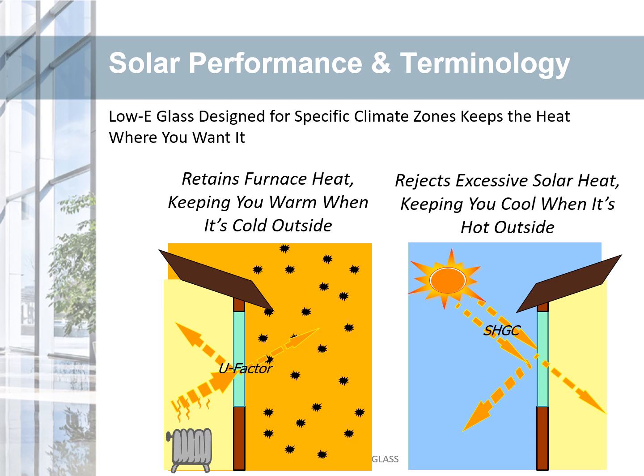Low E glass is designed for a thermal performance improvement. Low E glass used in fenestration products improves its U value. This improvement works in two ways. It can limit the amount of solar heat gain into a building in the summer in southern climates, or it can reflect heat back into a building in the winter in northern climates.